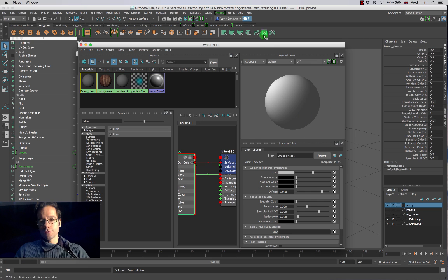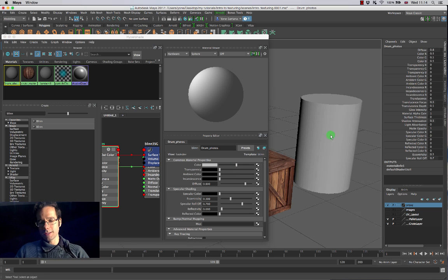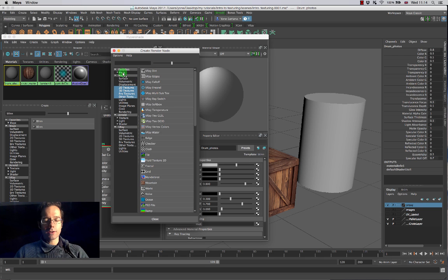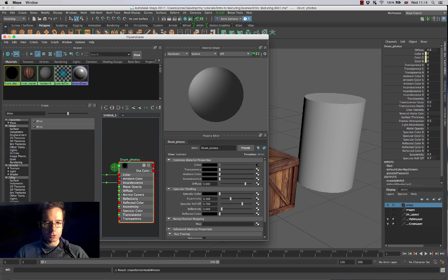Now with this image over here, what I'm going to do is, again, choose an image to apply to this cylinder over here. Now again, this is very simple stuff. We're just applying a photograph, adding it to the diffuse channel, or the color channel as it's called in Maya, and then we're applying it to an object. Now let's do very simply, again as we did, click on the little checker pattern next to color in the texture slot, and then I'm going to come over here and choose a file from the options, and inside the file, if I just happen to click on that, you'll see that there's this little playback button over here just because I tapped inside of the workspace, which is this area over here.